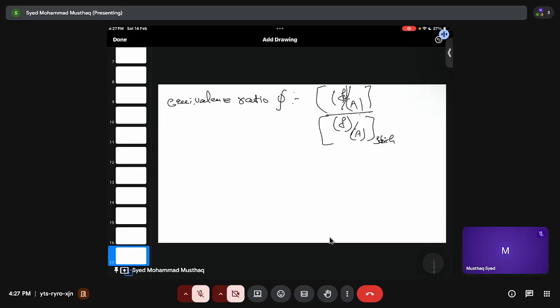This is the actual, I mean, that we have mixed, right? So this is fixed, this will not change. Now what I'm trying to do is increase air in my composition, then this value will decrease. So if this decreases, then this divided by this will again decrease. So phi will be less than 1, and we call them a fuel lean mixture, because it's obvious, right? Fuel is less when compared to the stoichiometric ratio.